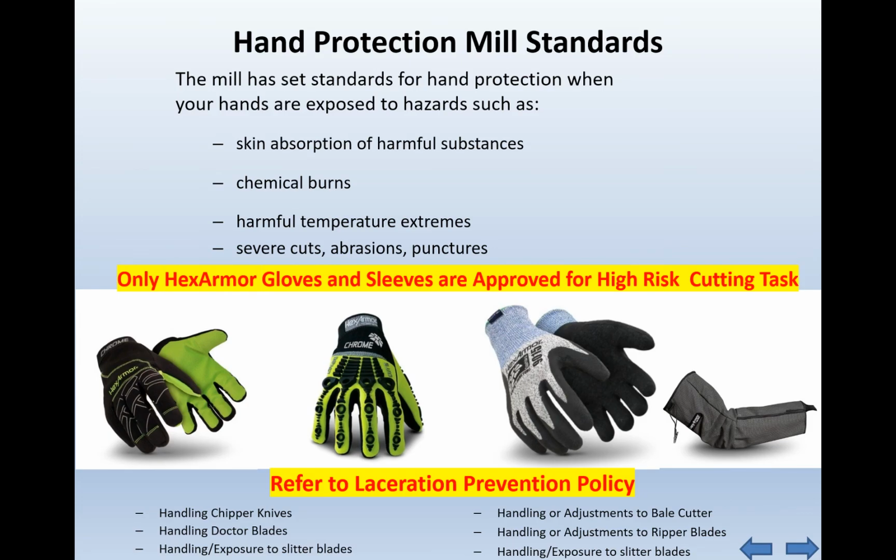The Hopewell Mill has set standards for hand protection when your hands are exposed to hazards such as skin absorption of harmful substances, chemical burns, harmful temperature extremes, and severe cuts, abrasions, or punctures. Only the Hex Armor gloves and sleeves are approved for high-risk cutting tasks. Refer to the laceration prevention policy when handling chipper knives, doctor blades, slitter blades, bail cutters, and ripper blades.